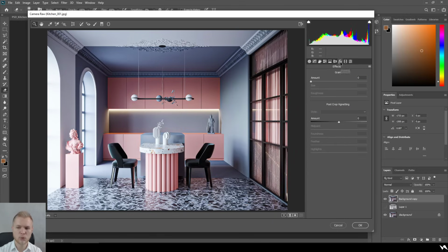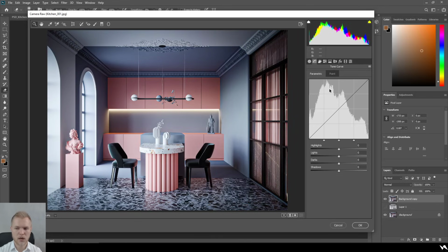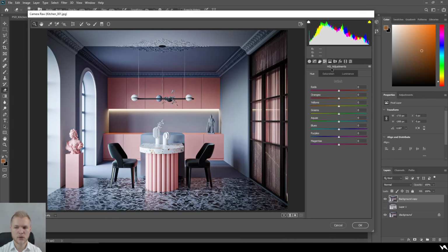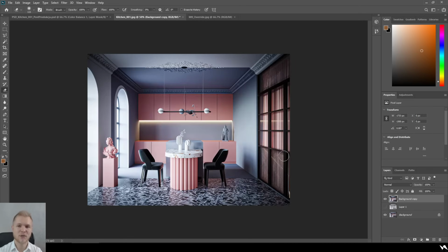But to get into a really photographic look, you need to add some effects like vignetting. That's always going to be very welcomed by your clients. Now, the last thing I always do is HSL settings. You can basically make sure that all the colors are set up to your needs. And if you need to change just a little bit the tone of your colors, or change something in your scene that just stands out, this is where you go. And now I'm not going to actually add any HSL settings, because it's just not necessary, because Corona actually is that amazing and it doesn't require you to do anything else than just go ahead and render. Now this is our final render, done almost solely with Corona renderer in 1 hour 20 minutes.